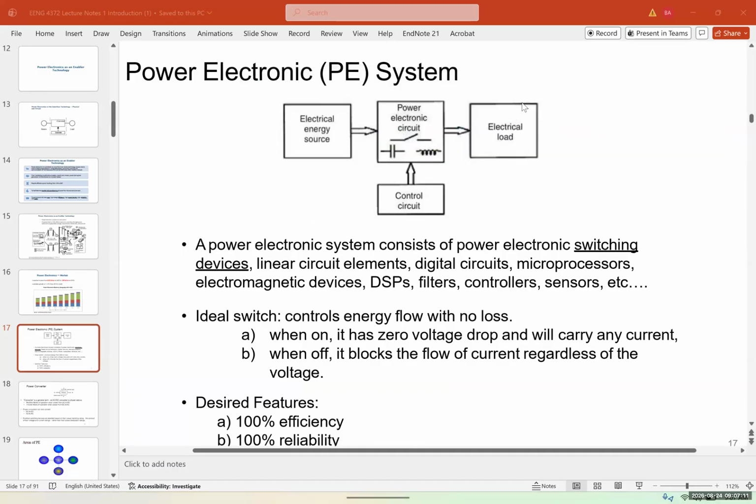we have different types of inverters. Most inverters that you see, which are car inverters, are not sine wave inverters. They are AC inverters, but they produce a rectangular AC. Now, for some applications, that's okay. If you want to charge your phone, your laptop, that's okay. But if you want to run a compressor, it's going to destroy your compressor in a week. If you have a fridge, if you have an HVAC, it's going to destroy it.